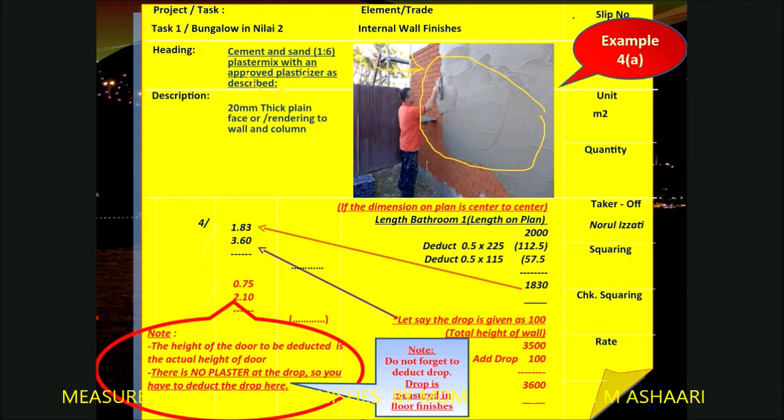This is a method of the application. And then remember, you have to write down the thickness of the plastering on the surfaces of wall and column. This is the example where you get the area for the bathroom by ×4 because all having the similar sizes. Okay, let's say the sizes are 2000 times 2000. So you measure by showing this dimension, okay, and then the story height, let's say, is given as 3.6.